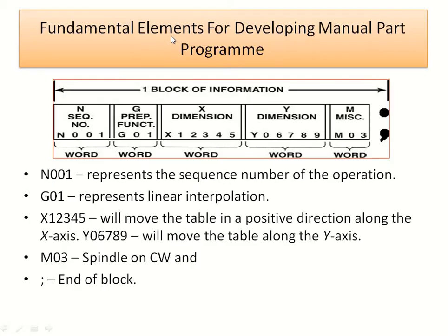So these are the fundamental elements for developing a manual part program with one block of information. The first word is N001, which represents the sequence number of the operation. The second word, G01, represents linear interpolation.